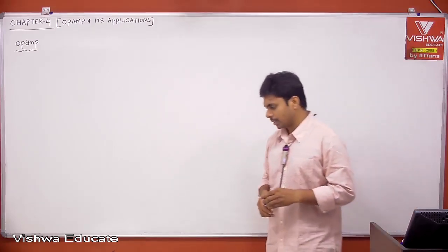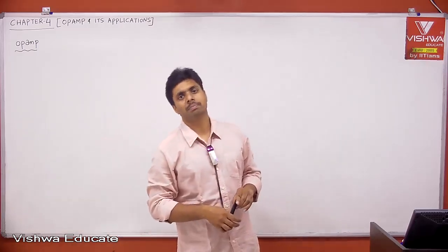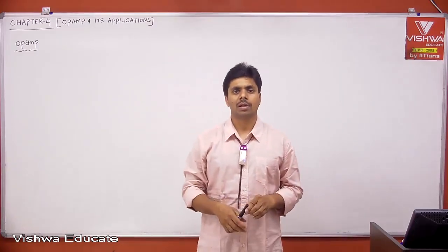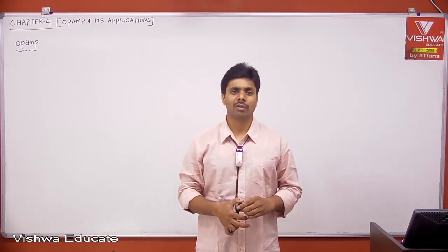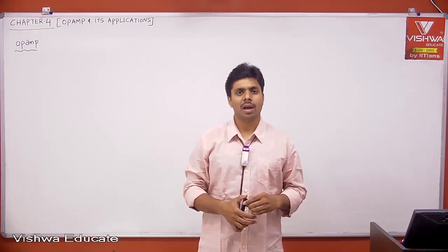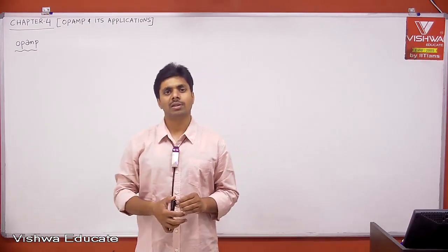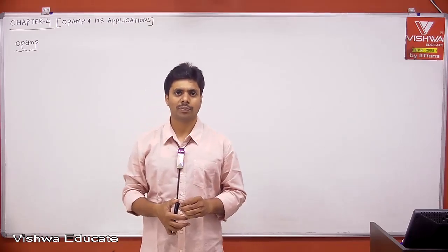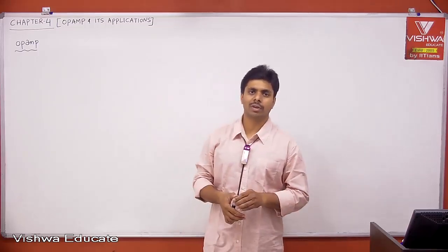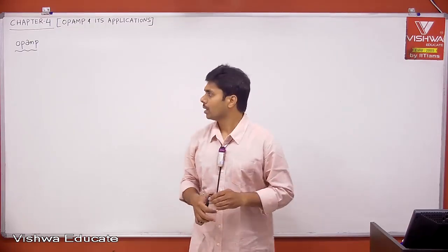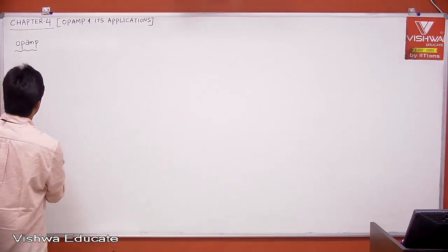I think from BJT amplifiers and FET amplifiers, we got to know that the final amplifiers are the best amplifiers we can get from your RC coupled CE amplifier and then RC coupled CS amplifier. We have seen the frequency response of the RC coupled CE amplifier, and the same frequency response is expected from the RC coupled CS amplifier. The limitation of the RC coupled CE amplifier is that low frequency signals are not processed with the gain we are expecting, which is the mid-band voltage gain.